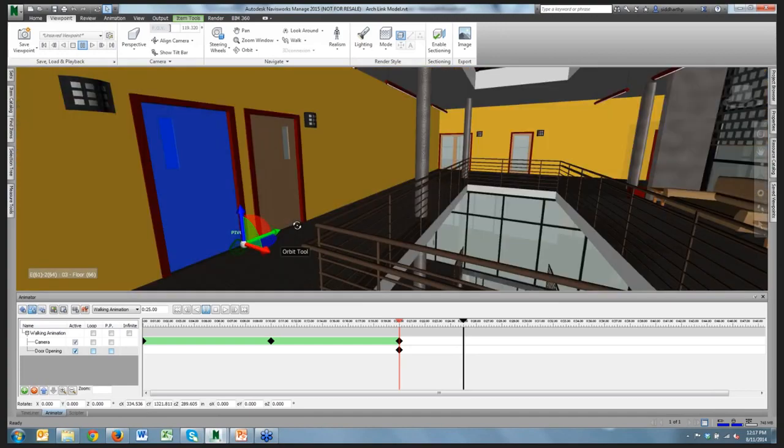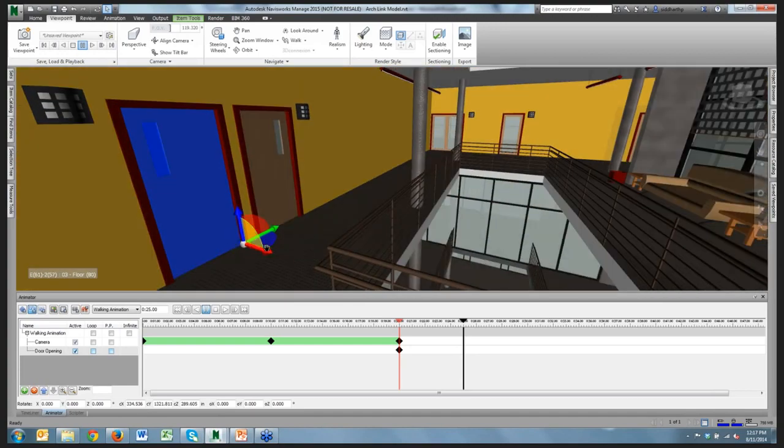And in some cases, you may have to line up the axis or just rotate this axis without rotating the object. Now, if I were to click on this plane, it will actually rotate the door about this vertical axis. If you want to rotate the grid here itself and not rotate the object, you can hold the control key and then move, translate the axis or rotate it. Okay, so hold the control key if you just want to control the axis. If you want to move the object itself, then you can just use the left mouse click and do that.